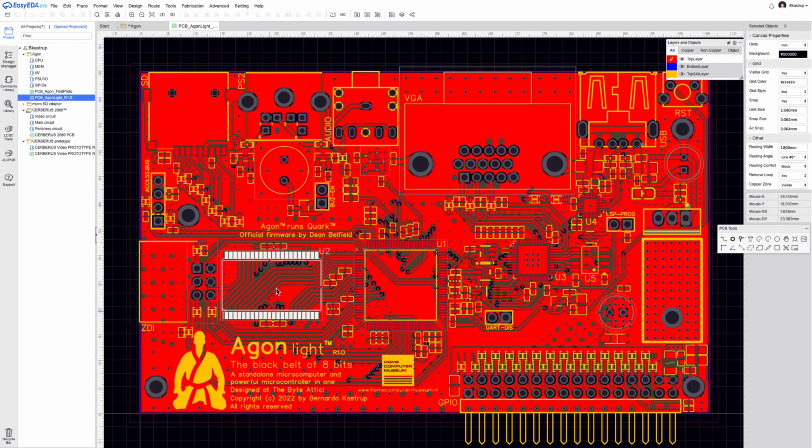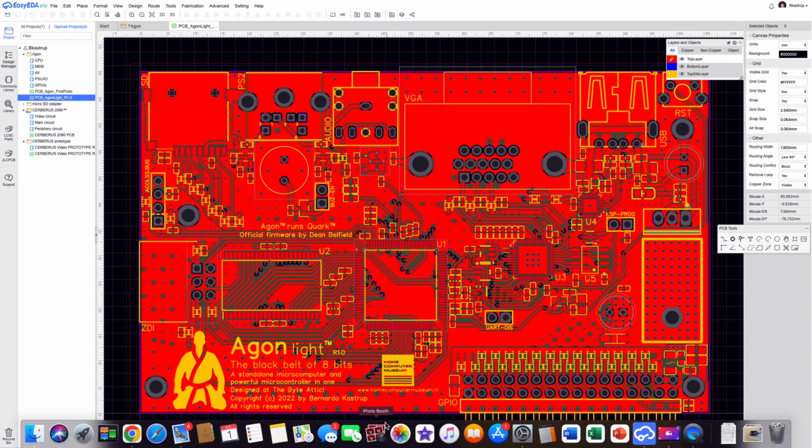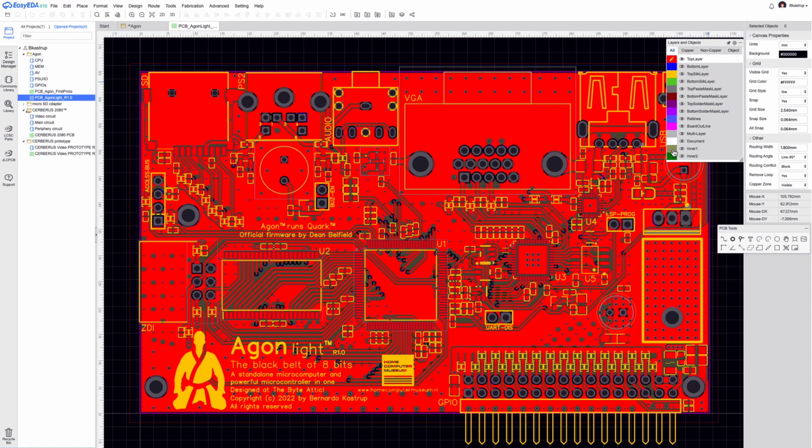For instance, in this part here, this has no bends. But if I would move this a little bit more to the right, I would have to create an extra bend. So you try to minimize the number of direction changes, and the direction changes you do need, you keep them at 45 degrees, and you keep the lines as short as possible, and then you try to make the board as thin as possible so that the top layer is as close as possible to inner one.